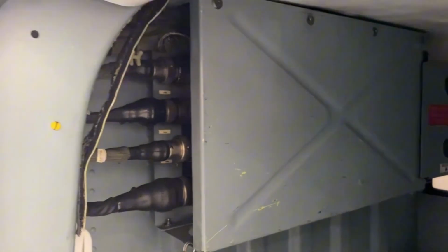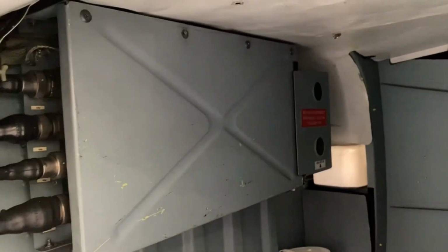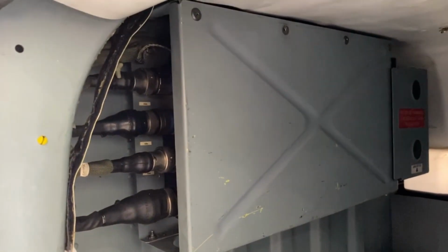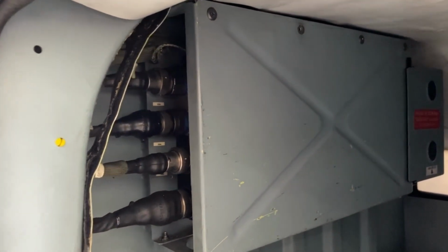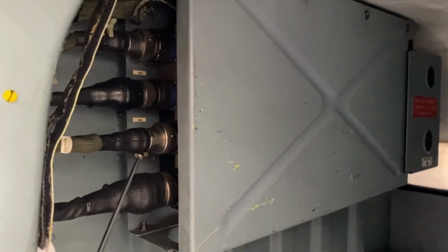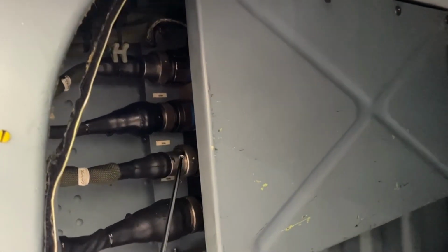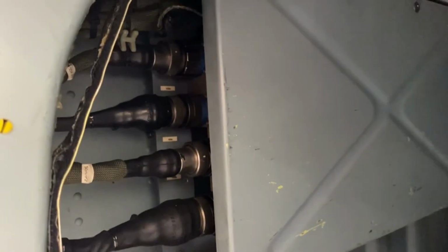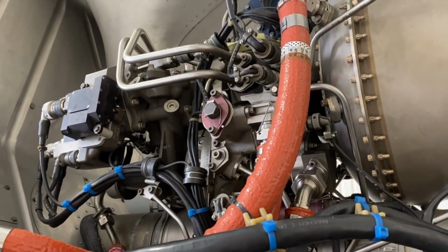This here is the aircraft's cargo compartment, the front wall, and all of this is the FADEC computer, part of the FADEC system, right? And here are the plugs, right? For input and output, you see those sensors we looked at. We have a sensor, a transmitter up here called XPA, which gives the pedal position, and there's a sensor in the control chain called XPC. So all the inputs and outputs are received here, meaning the FADEC computer is here, and the plugs are very close to the engine, with the engine at the top, right?